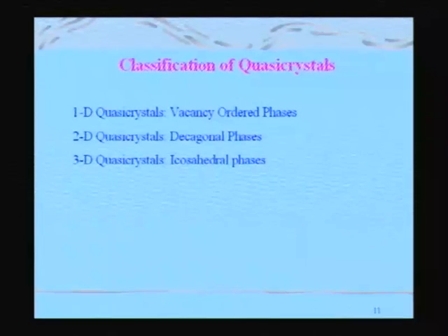the information from the second layer of atoms, because when you converge the electron beam, the beam will be more intense, and when it falls on the sample, you can find out not only the information from the first layer of atoms, but also from the second layer of atoms below that. From that one can get an idea whether really it is a 6-fold or a 3-fold. That's how we can find out whether it is a real 3-fold or 6-fold. And that's how here we can see, though it looks 10-fold, you will come in a minute when we talk about the classification of quasicrystals.